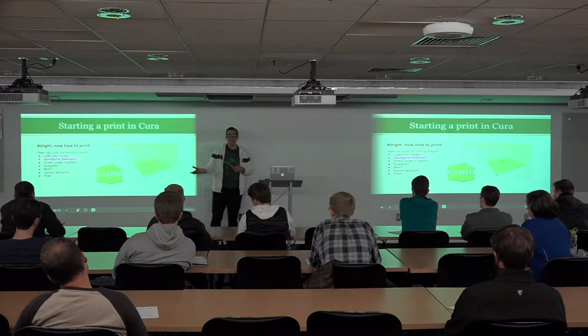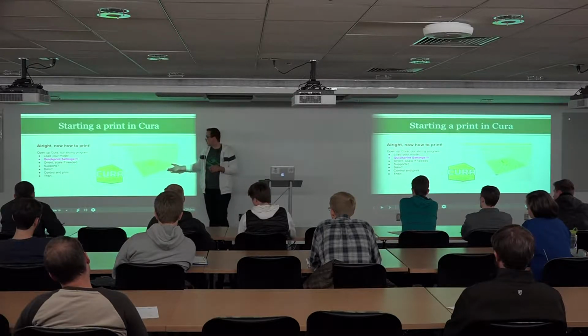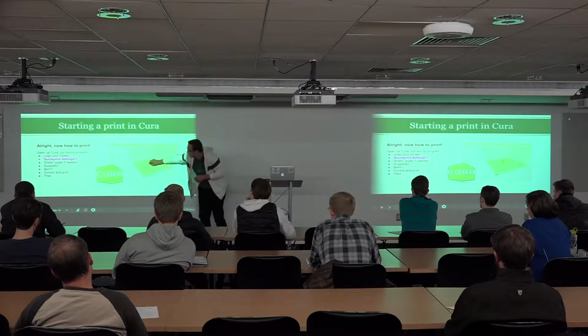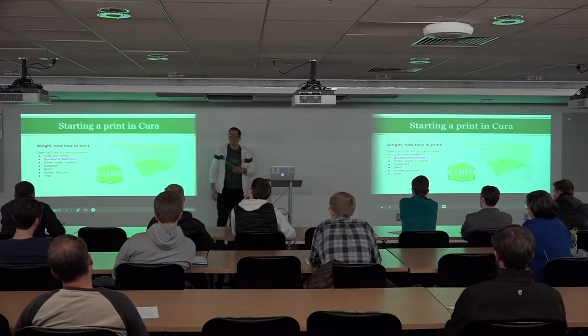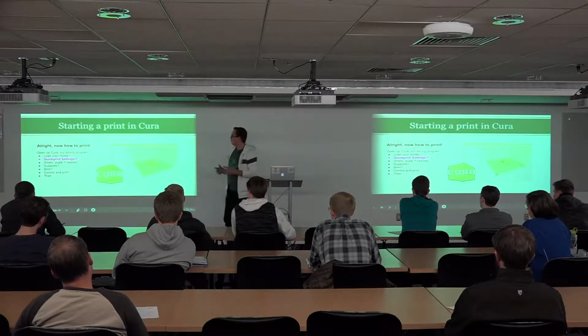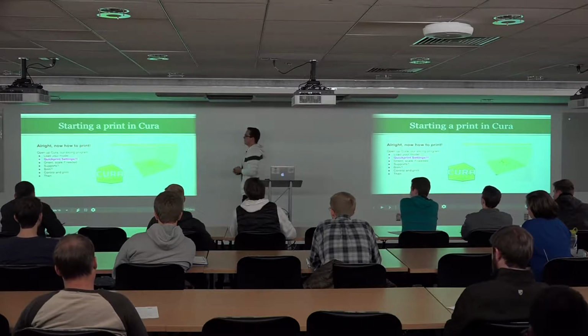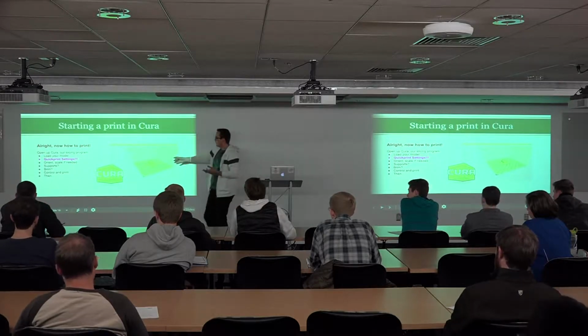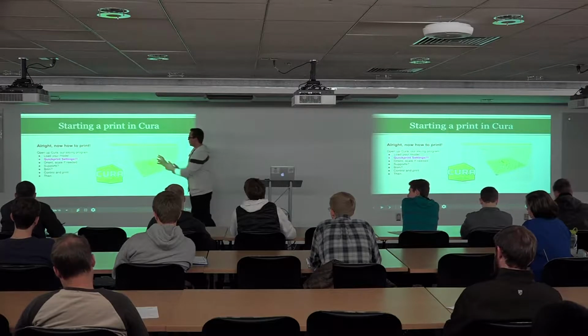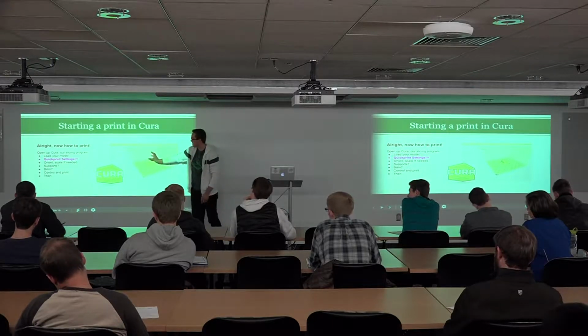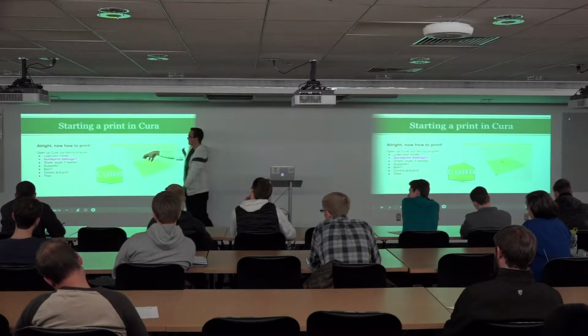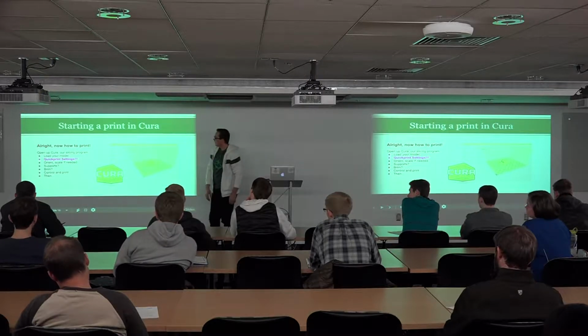If you designed it in inches, Cura thinks it's millimeters anyway, so it'll show up about this big. And you have to scale it up by 25.4, 25.4 times size. And then you can also rotate it if it comes in and you have a nice flat side you wanted it to print on, but it's oriented this way. You just rotate it down, and you're good to go.